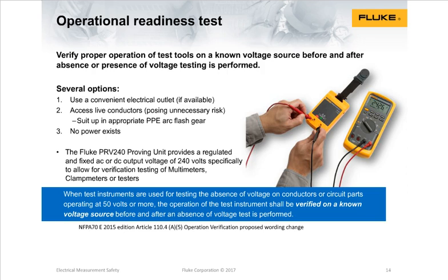One of the problems that we've seen is if you use lockout, tagout, and you cut power to a panel in a maintenance room or a machine room, once you've cut power to that room, typically they don't have an electrical receptacle that is accessible to make a proving type of measurement. So this is a portable supply that you can take with you to validate the operation of your test equipment. Whichever means you use, definitely follow that. They're also making a recommendation in NFPA 70E of direct contact with the active conductor to measure the available voltage.